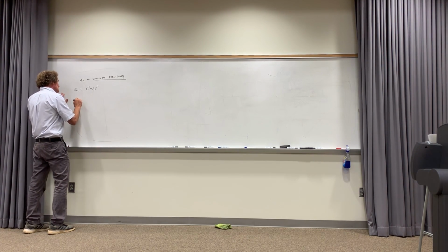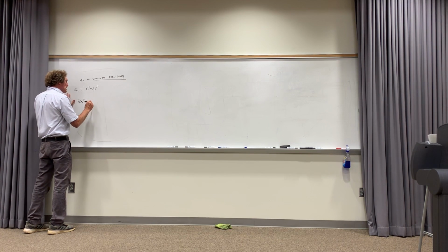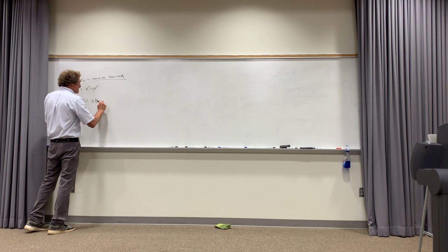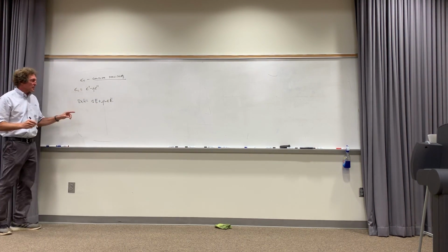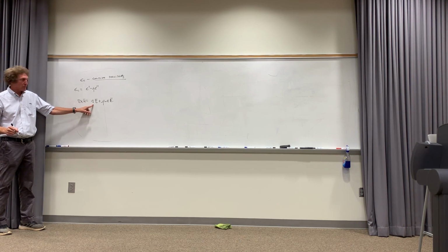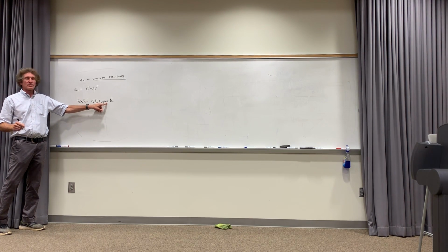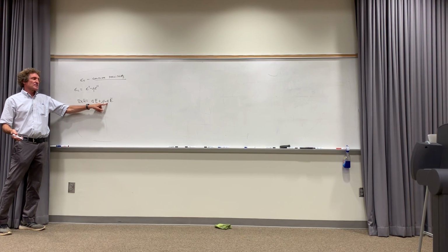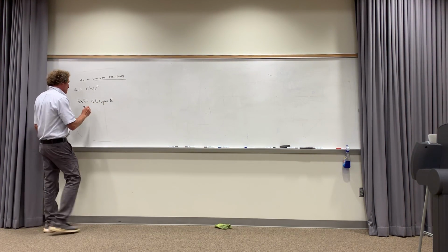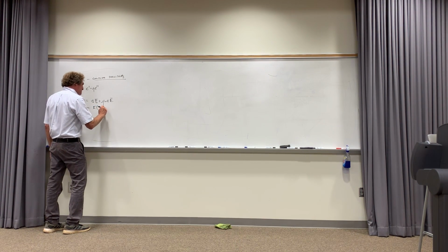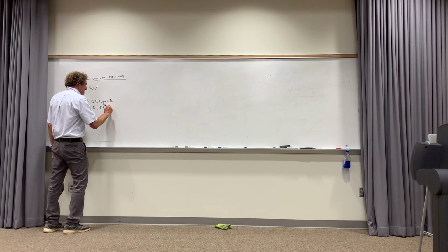So if you look at Maxwell's equations, curl of H normally was equal to sigma E plus J omega epsilon times E. Here what I'm doing is replacing J with sigma E, the way we did it before, and replacing D with epsilon E, and the derivative with respect to t with J omega. Furthermore, I can say this is E times sigma plus J omega epsilon, right?